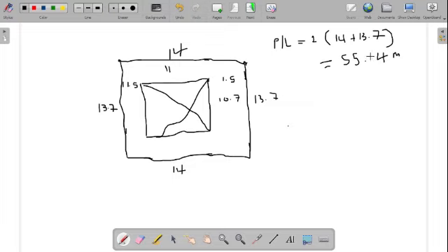But let us bear in mind, this 55.4 has been estimated on the assumption that the boards edges are touching each other, which is not actually the case on site. We have to consider that the board will have some lap joints, because for continuity, most times we'll lap each of the profile board. We have to consider that, because if that is not considered, the material we'll be estimating may not be sufficient. For us to do that, as a matter of experience, this measurement we have here is factored, and the factor we use for it is 1.2.